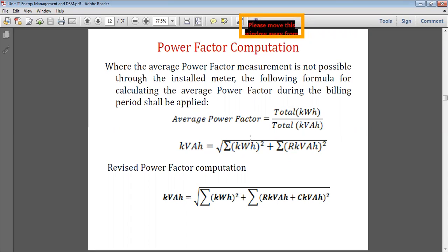So the number of steps has to be properly designed, so that it gives smooth variation in the power factor maintenance. Whenever you find fixed capacitors, it is necessary to replace them by APFC, automatic power factor controllers. Only a very small amount of fixed capacitor may be connected for the compensation of the transformer, and this should be connected before the APFC. So it will take care of the leading lagging kVAr drawn by the transformer only, whereas the load change is going to reflect in the switching on and switching off of the capacitors. So this formula we have to remember.